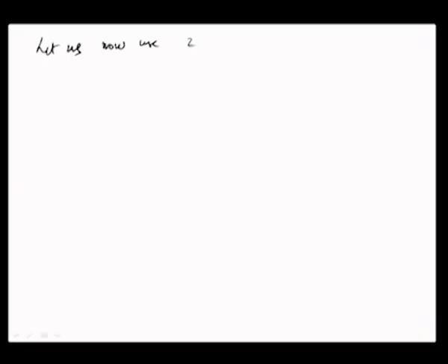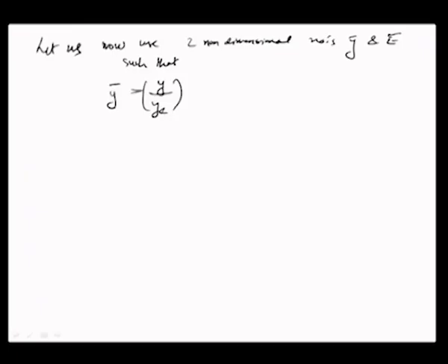use two non-dimensional numbers, y dash and t dash, such that the value of y dash is represented as the actual y divided by the equilibrium gap. In other words, this gives an idea of how many times the equilibrium gap is the actual gap between the tool and the workpiece at a certain instance of time.